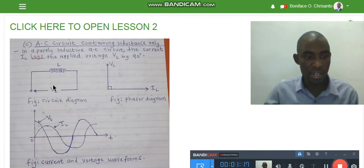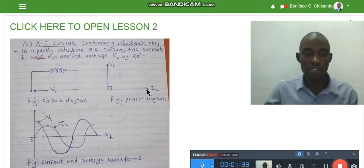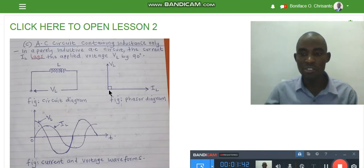So in the circuit diagram, the voltage source and the inductor are connected in series. That is why we say this is a series circuit. This is the voltage source, this is the inductor. And because it is a series connection, current is the same. Because current is the same, whenever you draw a phasor diagram, current is drawn on the horizontal scale.